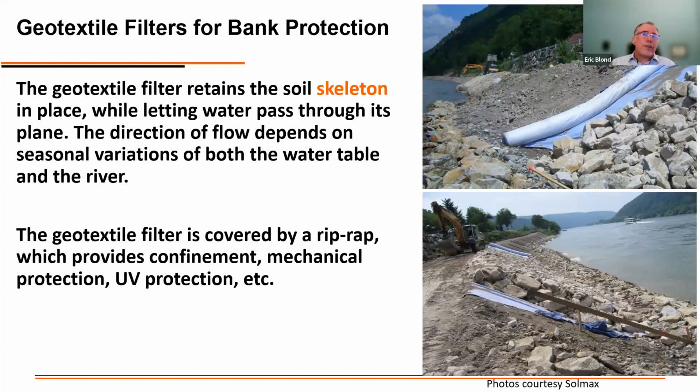In that case, the geotextile filter is going to be covered by riprap, which provides confinement, mechanical stress on the fabric to prevent it from being removed.